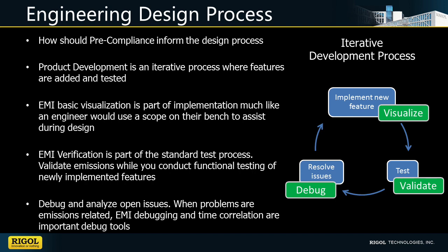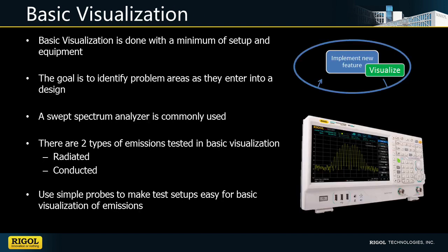So first, let's go ahead and look at visualization. In basic visualization, we're trying to visualize emissions issues as we're implementing new features. The goal here is really to identify problems as soon as they enter into a design. We can solve problems in real time, and make sure we're not causing any issues that we're unaware of. Typically, we'd use a swept spectrum analyzer in this kind of mode, and the goal really from an EMI pre-compliance standpoint is a simplified setup.